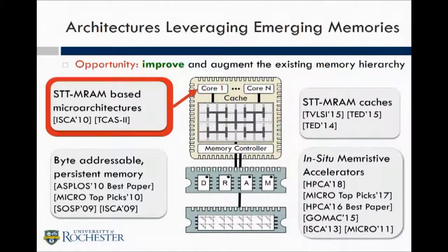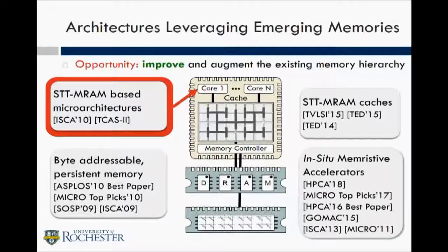You can also take one more step, and you can say, hey, maybe I can push these technologies deep into the micro-architecture of an out-of-order core. And when you do that, a lot of the structures that we use that are performance critical, like load store queues, register files, rename maps, reorder buffers, and so on, actually become better in the sense that within a fixed cycle budget, you now are able to have much more capacity because the technology is denser, so you can exploit instruction-level parallelism much more aggressively. All of these would be examples of fitting within the existing paradigm with these new technologies.